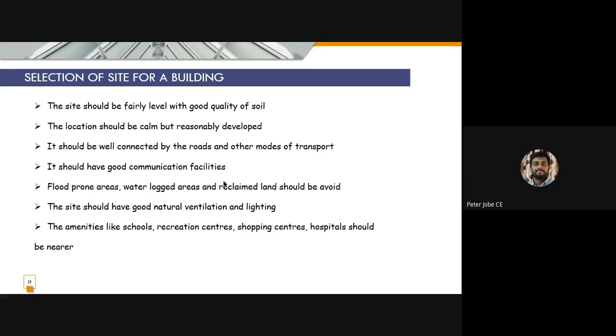For example, if we go to a lakeside or a riverside, we can find a lot of clay soil over there. Especially if we go to the Cochin region, the type of clay over there is very unstable. But it is such an economic area where it is essential to build various structures. We can't just say that we cannot construct a building over there because the soil is clay in nature and won't be stable. The only thing we can do is stabilize the soil using various techniques.